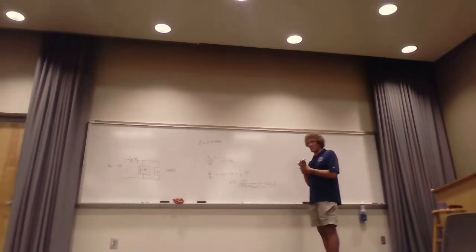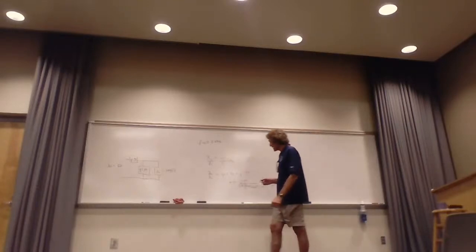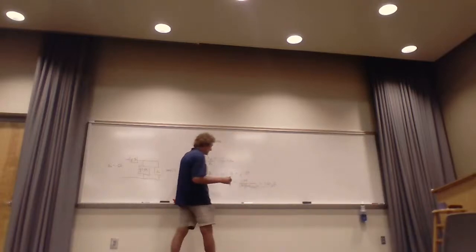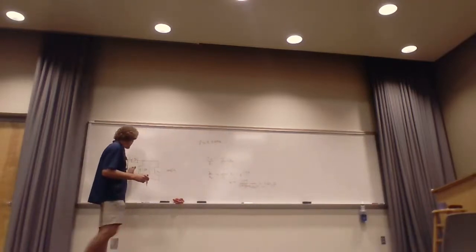I'm just warning you, when you're working around these things, it's good to have a feel for how sensitive the part is to lead length. This thing's going to be very sensitive. 1.69 picofarad is not much at all. All right. Next, we're going to get the inductor.